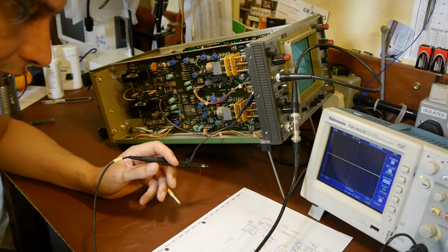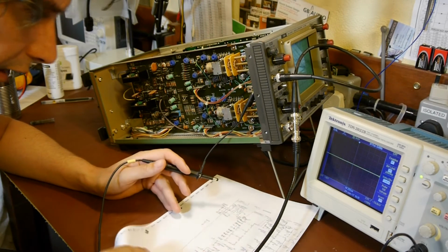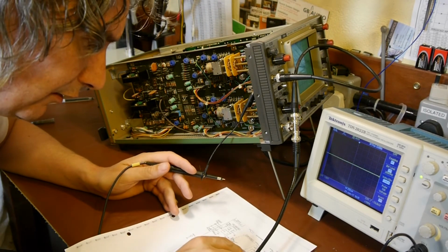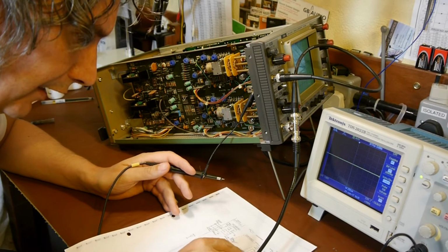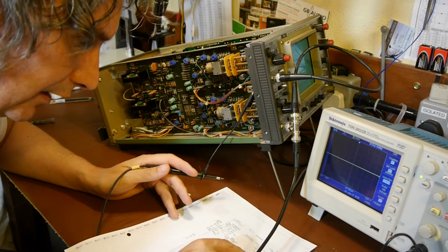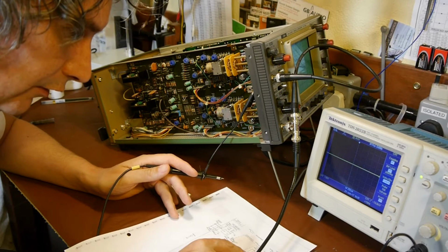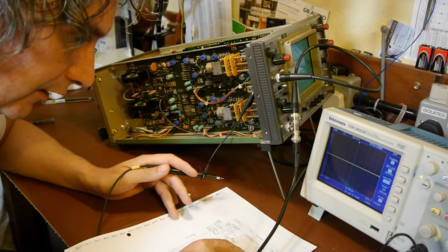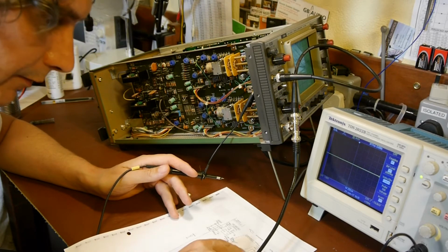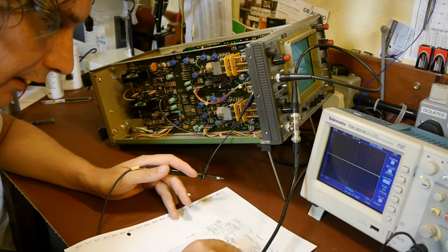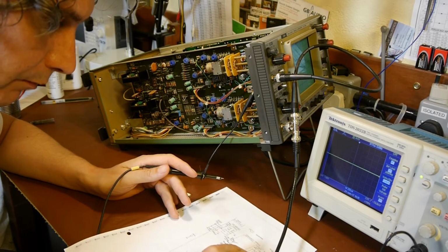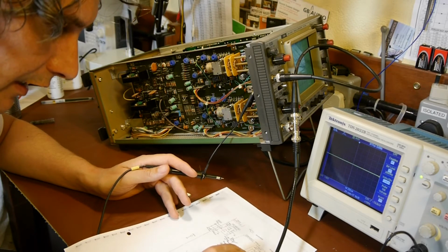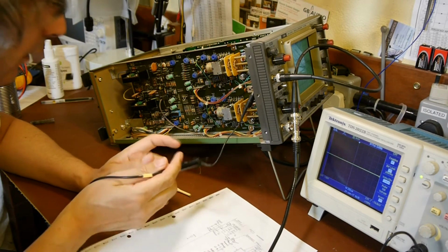So we need to find the output of these attenuator circuits, and it looks as though the outputs are being developed across, for channel 1, R008, and the way the circuit diagram works, they've got the channel 2 one printed next to it. So the resistor for channel 2 is R108. So let's look at 008 first.